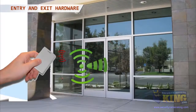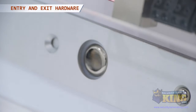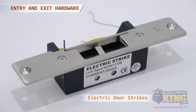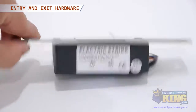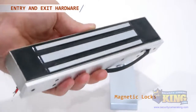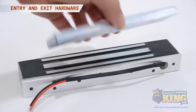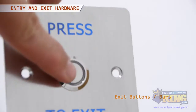Once the user has been granted access, it must send a signal to the door to unlock it. In this case, the door must have special equipment that works with the access control system. The 2 most common mechanisms are electric door strikes and maglocks. Electric door strikes. These will replace your existing door strikes. They are electric powered and will automatically unlock when the user is granted access. Magnetic locks. Maglocks are electric powered magnets that will hold the door closed until the system sends a signal to unlock the door.